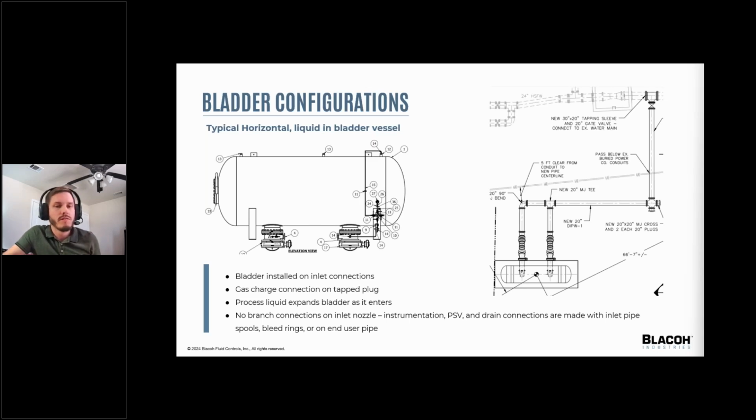It's just a real general rule of thumb: you want to keep your overall length to diameter ratio less than 3 to 1. That's basically due to the weight load of the bladder itself if it's suspended in a vertical vessel, and age of water issues on a horizontal vessel, hydraulics. There's a few reasons for that, but we typically try to keep it less than 3 to 1.